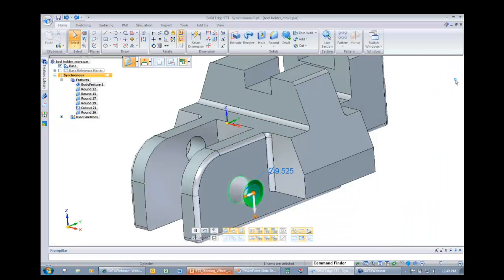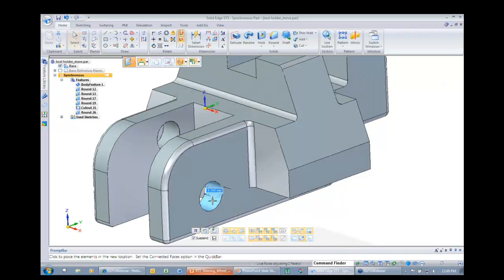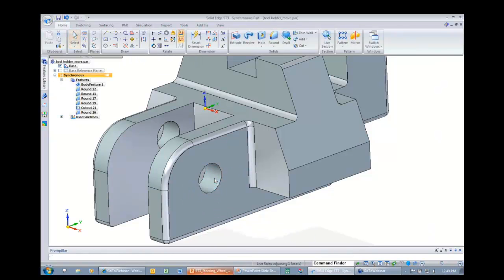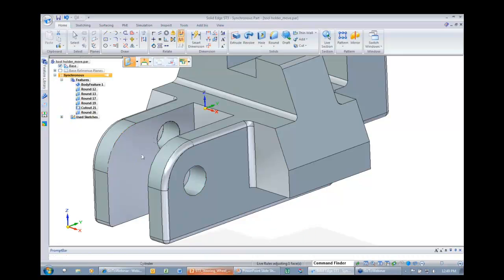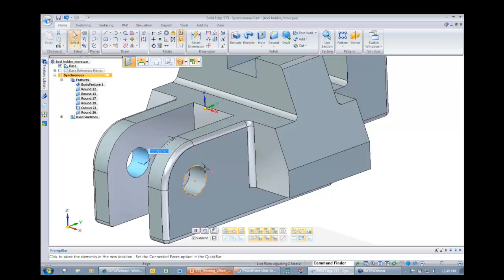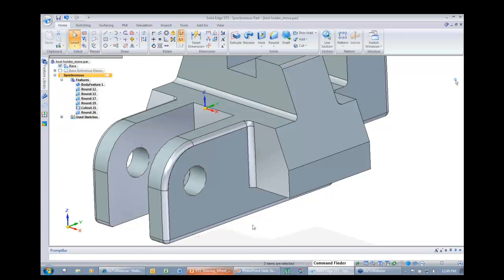You see the 2D steering wheel, when I select this hole, I can move it, you know, X and Y, so to speak, with the cardinal points, primary axis, like you would expect. The other thing, if I click inside the tool plane, notice how I can kind of move that along the face all in one movement. So it knows it's tied to the face. I'm moving it. It's kind of like move face within plane. I can come up here and say, put that on a center point. If I click this particular hole or cylindrical face, I can click inside the tool plane and quickly come up and say align those. So I'm using that within plane inside the tool plane option.